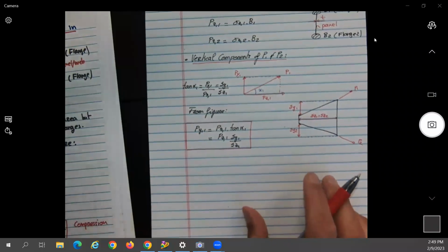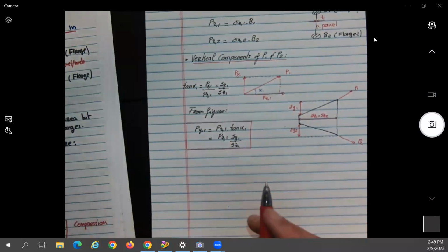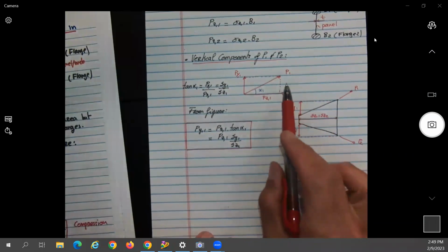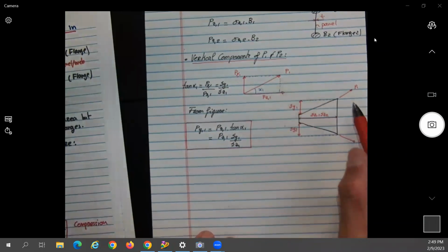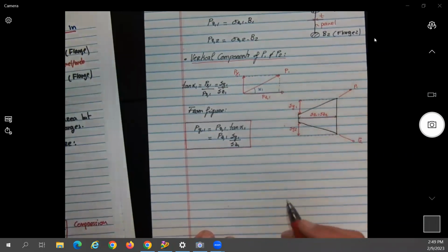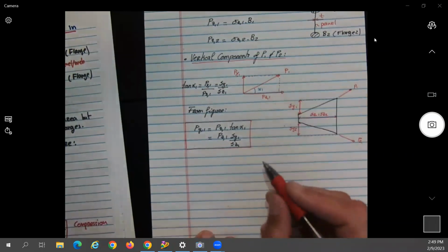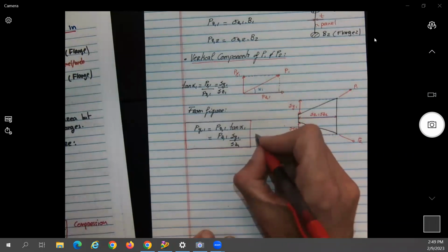Again, here I'm going to give you the choice. I don't like to put signs, but remember, if we say this side was in compression, really, this axial force should be pointing in what direction? To be pointed in, no? Okay, so you can write over here, in this case, this is compression.